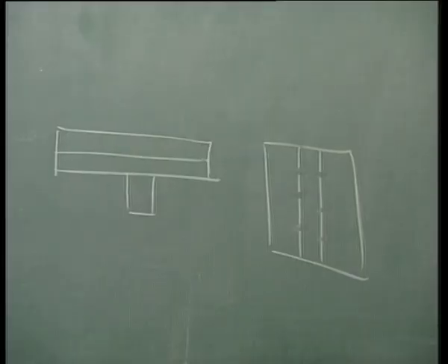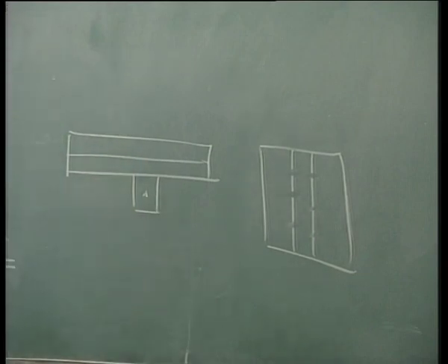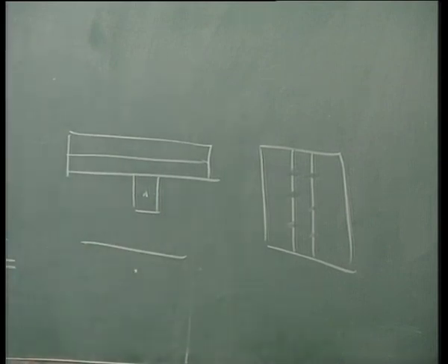Where would I do it? Where would I do it for a beam element? I have to do this at the center or centroid of the beam. So when I reduce the situation to a modeling situation, what would I ultimately have? I will have one plate element like this and one beam element like this. This is the view perpendicular to the board. Is that clear? Okay.